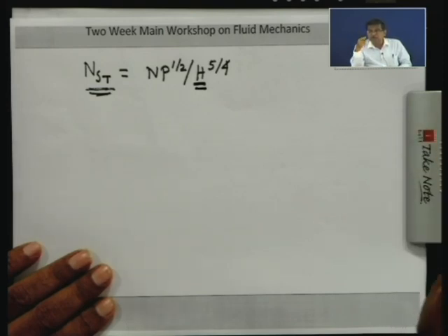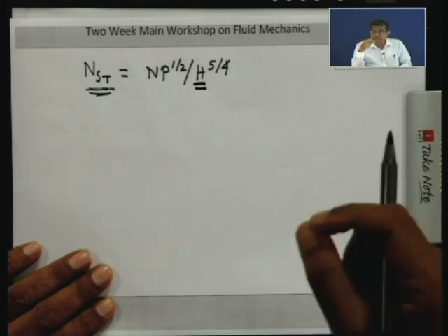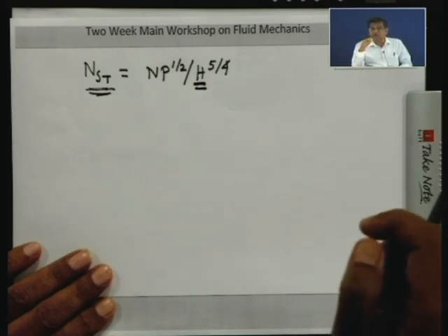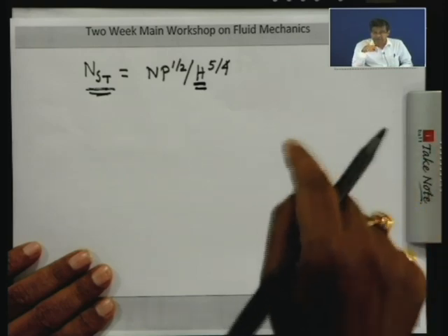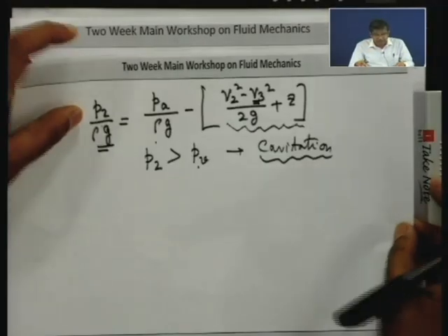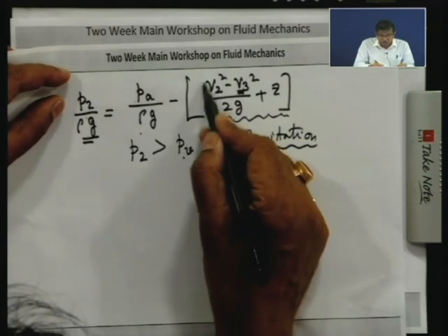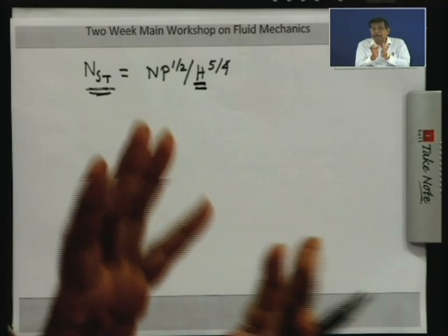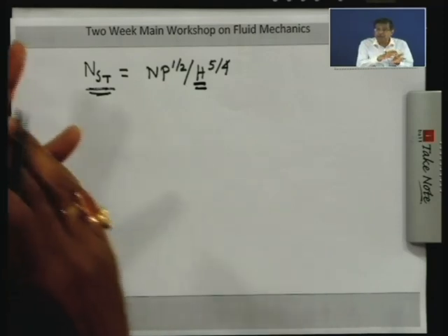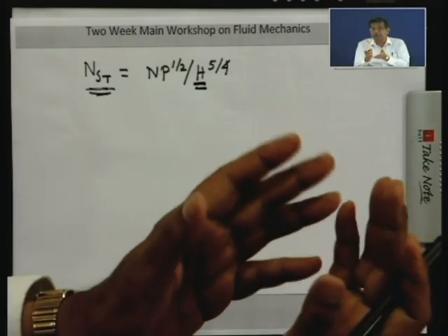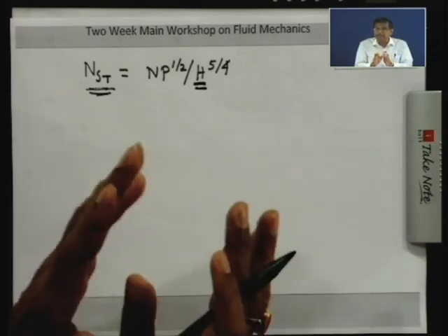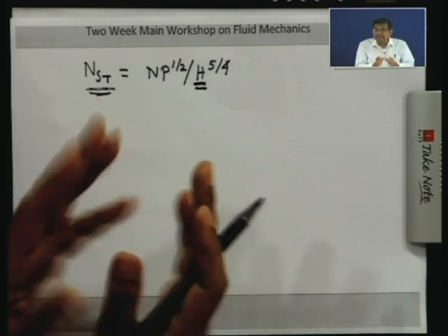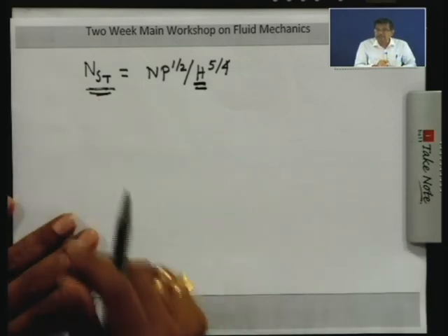At the same time, with the high flow rate, the velocity at the runner outlet has to be low, because we have to avoid cavitation. So it should accommodate a high flow rate, so that even at a lower head it can develop substantial power efficiently, but the velocity at the runner exit has to be low. These are the considerations to be made to design a runner blade.